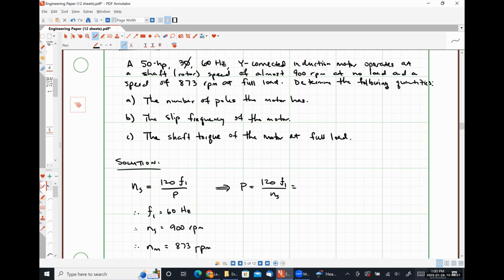So plugging in numbers, we have 120 times 60 over 900. So what's that give me? Eight, absolutely right. 8 poles.